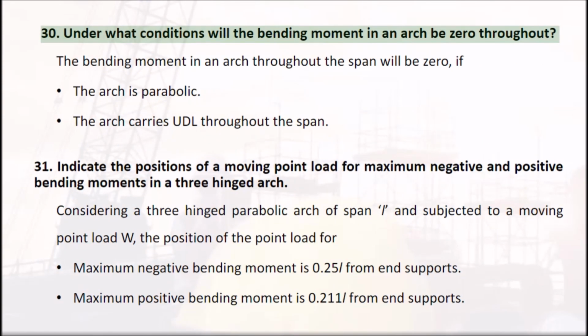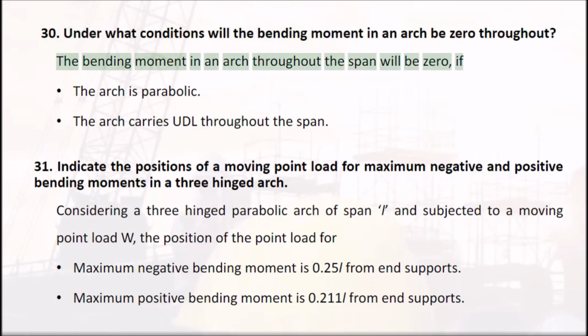Under what conditions will the bending moment in an arch be zero throughout? The bending moment in an arch throughout the span will be zero if the arch is parabolic and the arch carries UDL throughout the span.